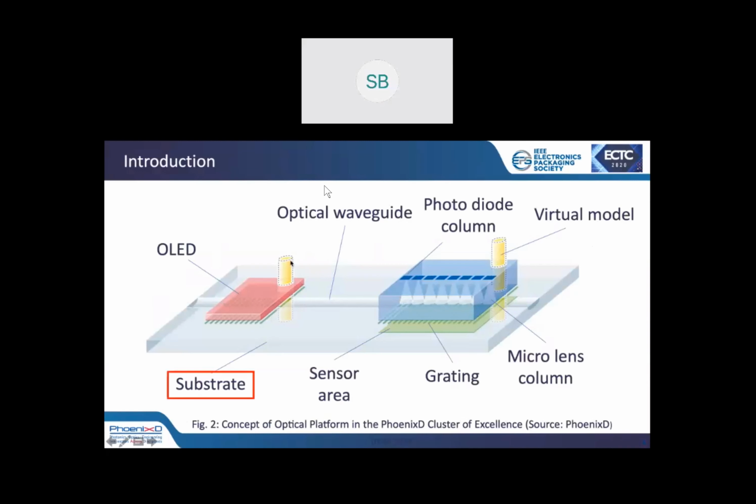So therefore we could create very small structures on top of a steel substrate or even on the nickel substrates, nickel structures. In this picture, you can see the optical quality of our gratings. You can see the diffraction in these pictures. You can see the different colors. And this picture shows the large gratings we created, still using common lithography processes, using UV light. These structures are at a diameter of 2 micrometers, but also we already can show optical qualities.